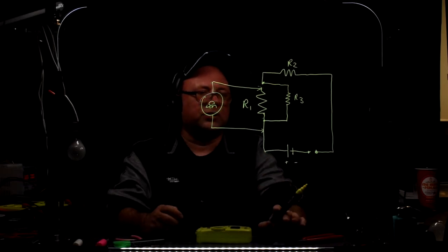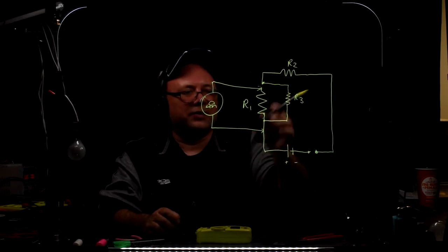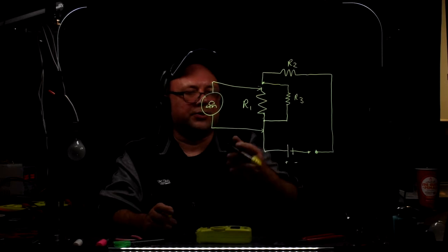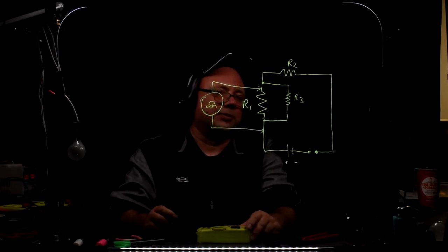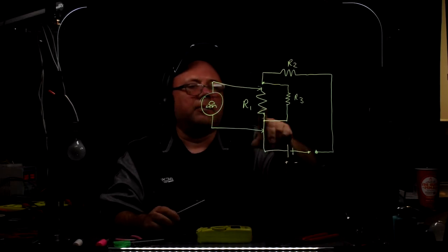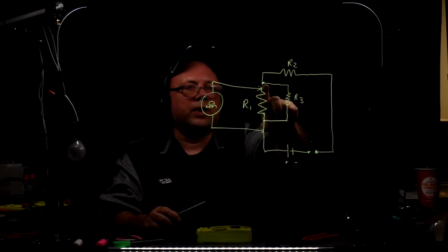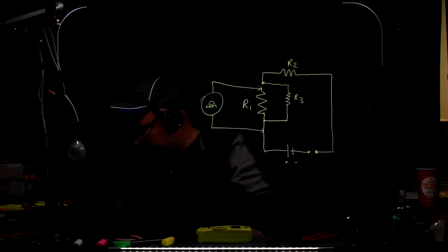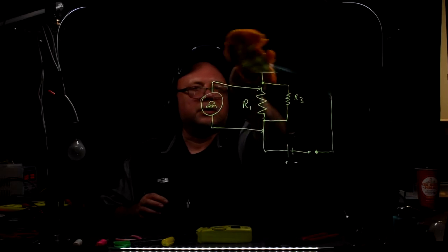Now, if you're using an oscilloscope to measure something else across that resistor, then you might want to take the whole part out, because the oscilloscope sometimes has a floating ground, and sometimes you don't know if the ground is connected to something else. But if you just have a freestanding ohm meter, you can just lift one leg of the resistor. So that's what it means to de-energize the circuit and remove the component out of the circuit.